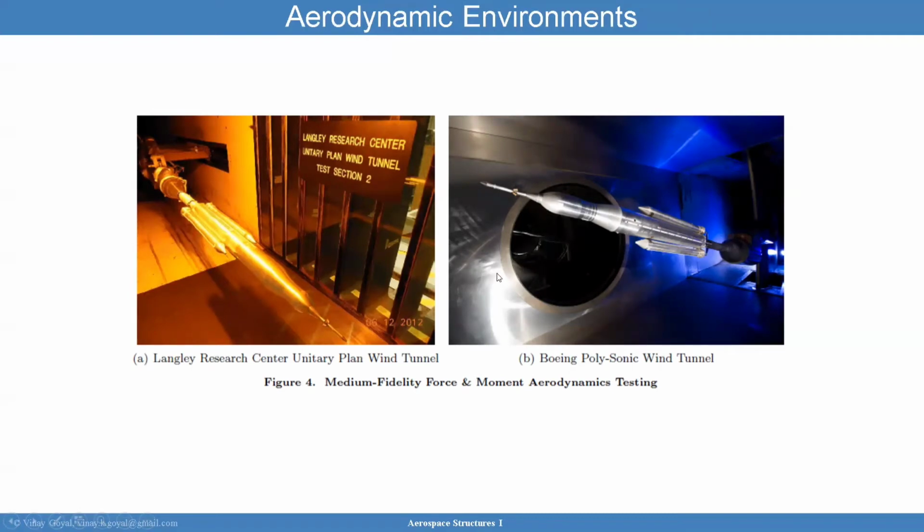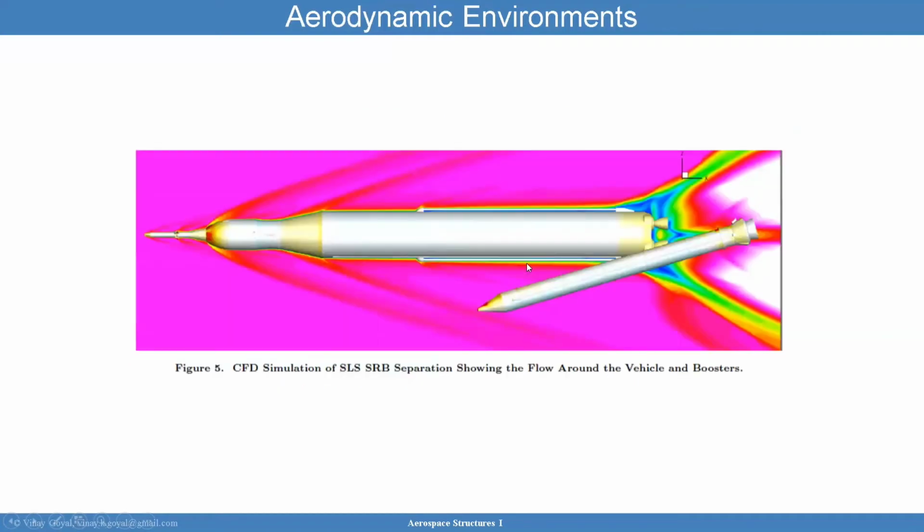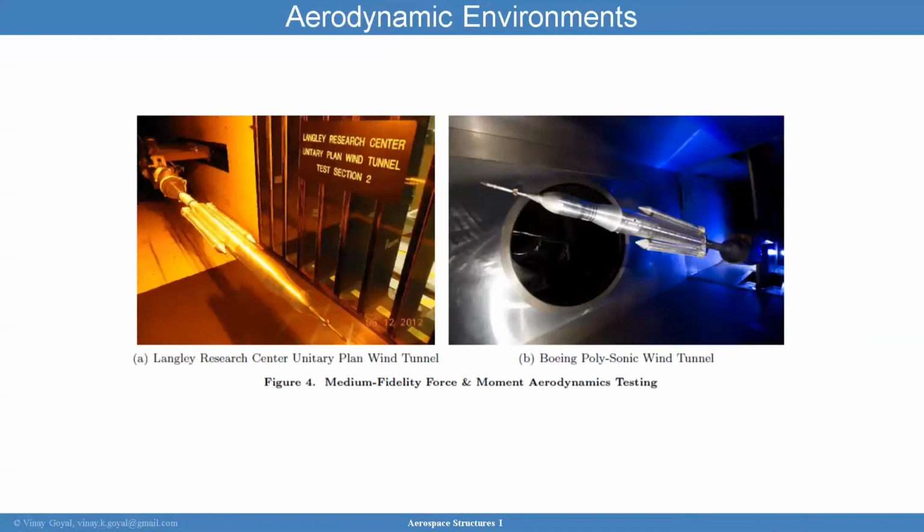This medium fidelity force and moment aerodynamic testing can really provide a lot of information on the vehicle dynamics and the loading environments that you may see. So that's quite important. I want to point out that the aerodynamic induced forces and moments in this kind of test are one of the first aerodynamic products that engineers use to predict the vehicle control, trajectories, payload performance, and so forth. That's why it's so important to get this data right, and you can use previous databases to inform that.